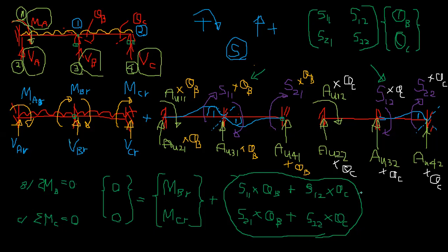So this is the S, meaning the stiffness. So this part I can write as stiffness into displacement. So this is the displacement matrix. Okay, so I can go ahead and write this whole thing. The equilibrium of the original structure at each joint was 0, right? So I'm writing it in one line. There were two elements, so both of them were 0. That's why I'm denoting it as a zero matrix.